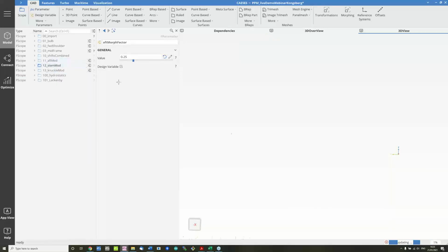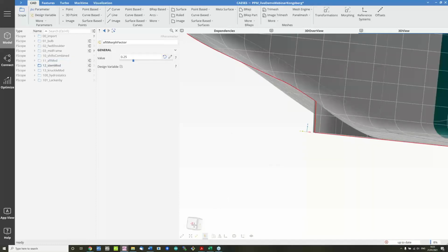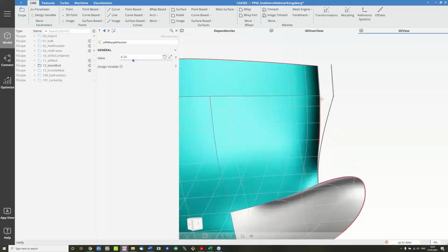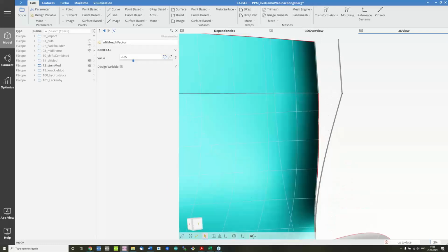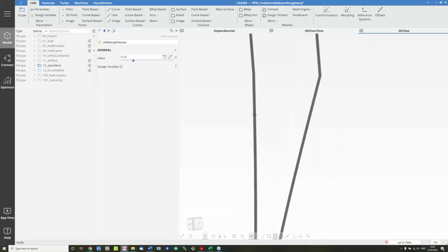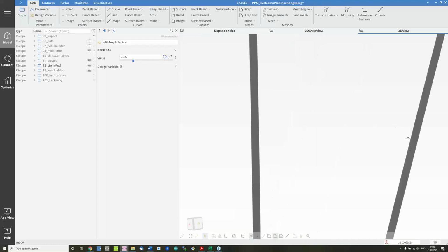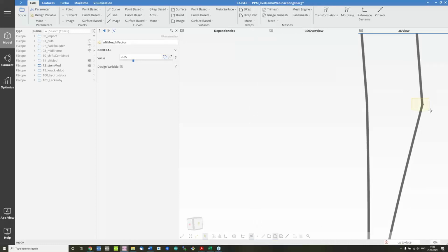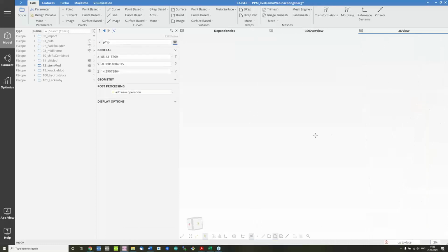I've set up another example here in which I decided I would want to modify the shape of the stem. In this case, I've used surfaces as sources and targets. So if I hide that BREP, you can see that there's a small surface over here, and then I've manually basically created this new surface over there. I can control this by moving a point in space here. If I want this to look differently, I can just bring it back and forth.